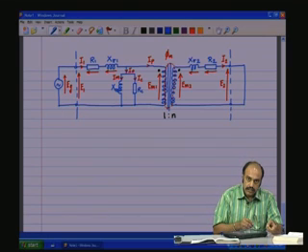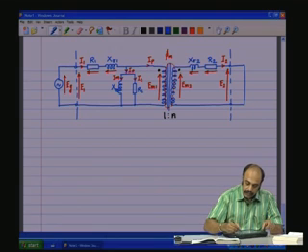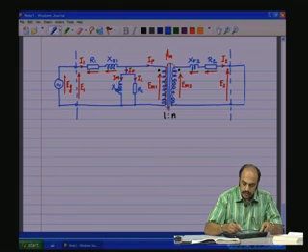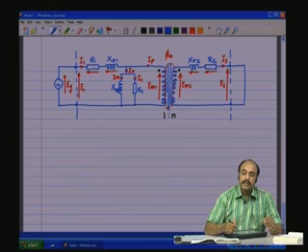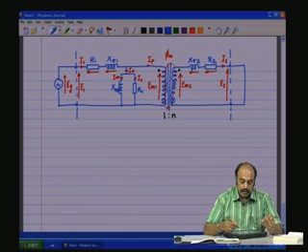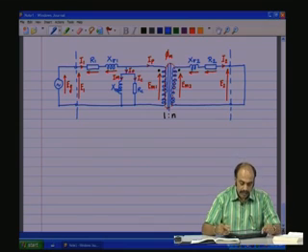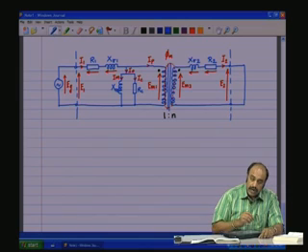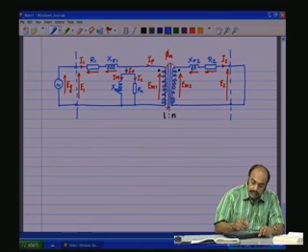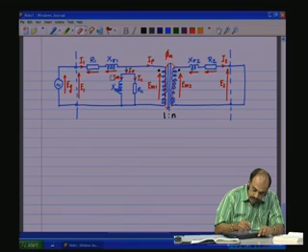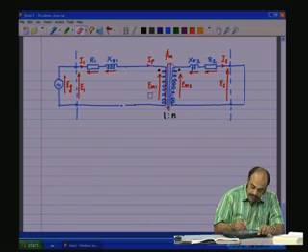You just keep increasing the voltage till the rated current, or the nominal current, flows through the secondary, and take the measurements at that time. The measurements can be taken quickly so that the transformer does not heat up. Under the short circuit condition, we see that the I1 will be much higher than the I naught, and therefore, they can be neglected. So, these portions will vanish as they are negligible.